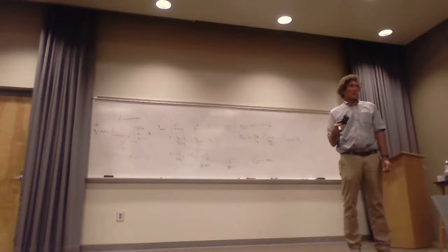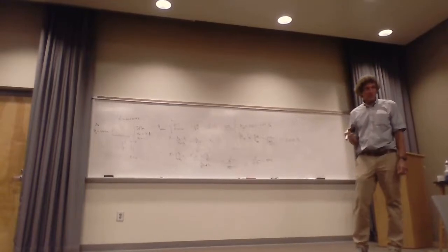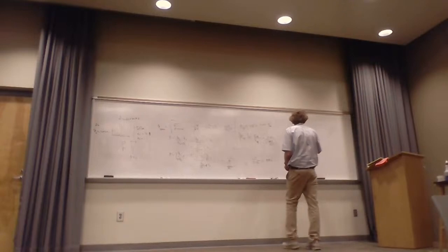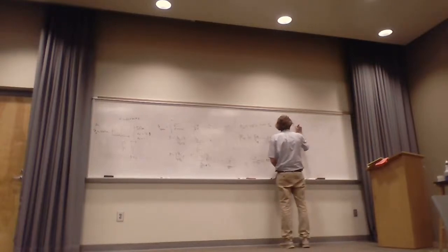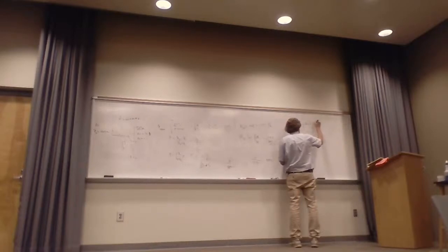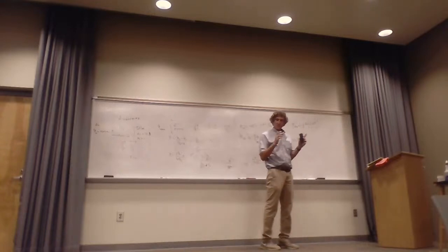Yes, in the Teflon. All right, the Teflon has no loss, right? So the intrinsic impedance is strictly real. Do you all agree with that? And we know if we want the average power, P average, technically it's 1/2 the real part of E cross H conjugated. If we wanted to be formal, we could introduce a coordinate system and do all that, but we don't need to.